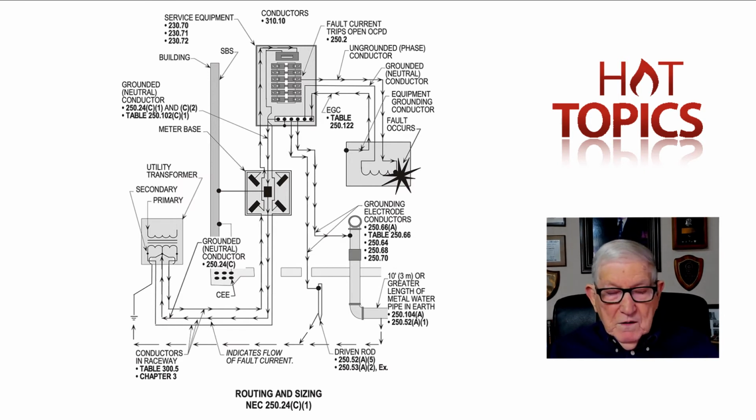Now notice you can pick that up on page 35 for both of them. But the grounded conductor, and you say, well, what is that? Well, say that this transformer, we're just saying this now, is 480/277, but when you bring the 480 and 277 in, it's only equipment, 480. A lot of times people say, well, I don't have no neutral. I don't have a 277 volt neutral. And sometimes they'll just leave that neutral out. And we're finding that today, and it shouldn't happen. But where people are installing this equipment, they have not had the experience and the time to learn these things.